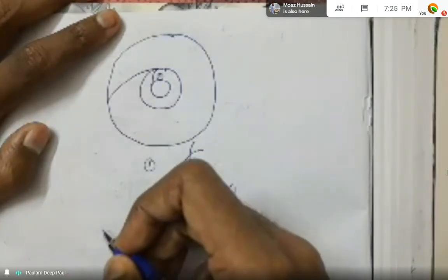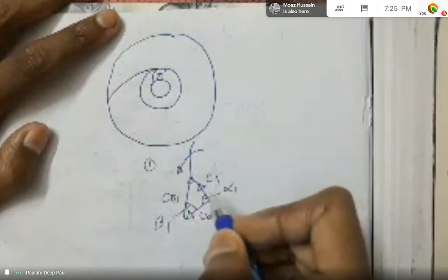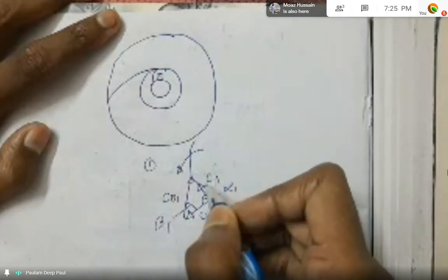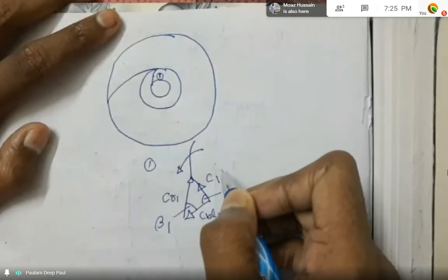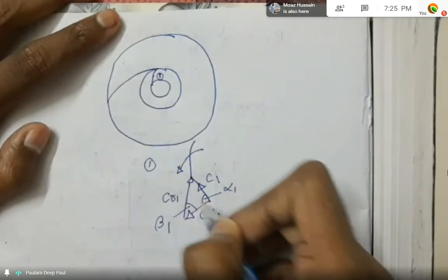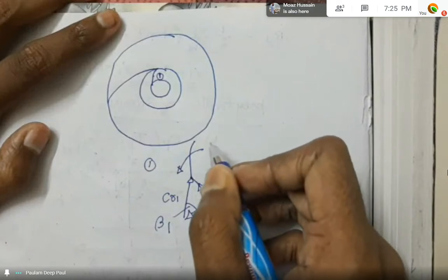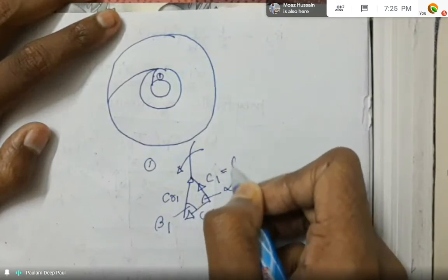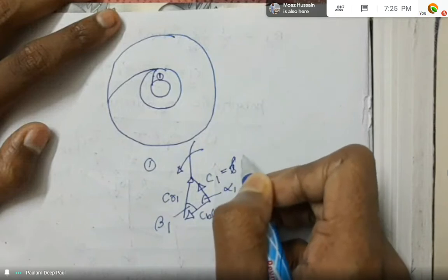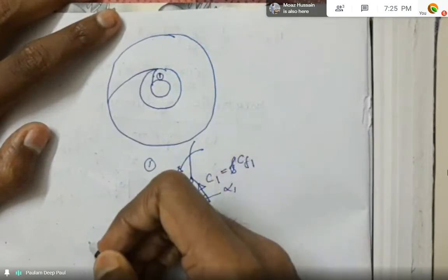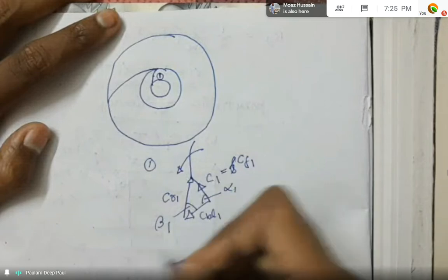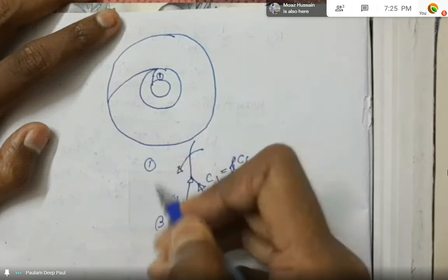We also see that there is no whirl component here, because it is entering the centrifugal compressor in the radial way. So the absolute velocity is equal to the flow velocity component, and we do not get a whirl component here, as in CW.